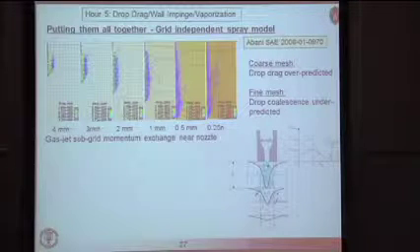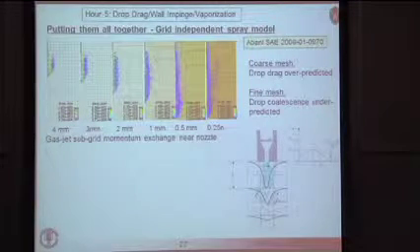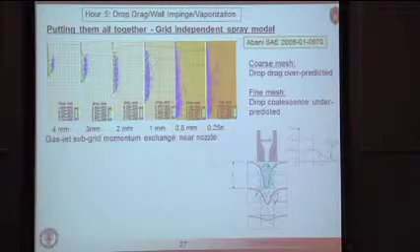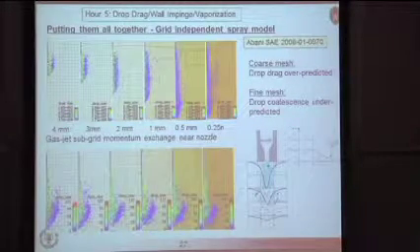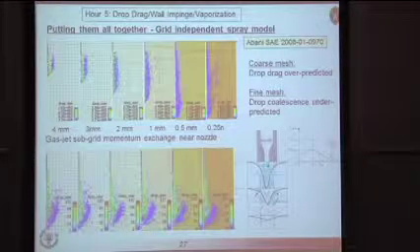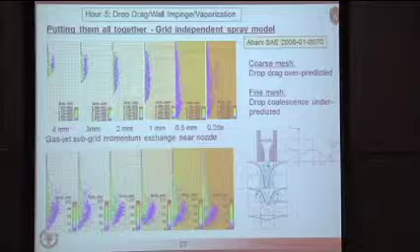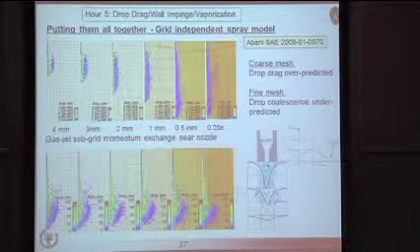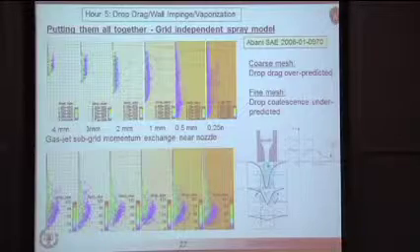And when you do that, you only have to do it in those cells very close to the nozzle where you don't have adequate resolution. We find we're able to match the spray penetration adequately over a wide range of mesh sizes. So you can think of this as a sub-grid scale momentum exchange model for large cells.